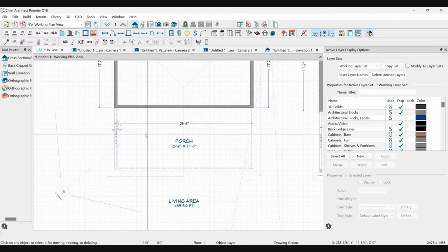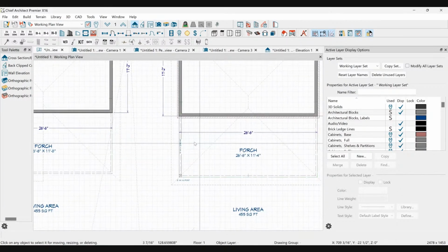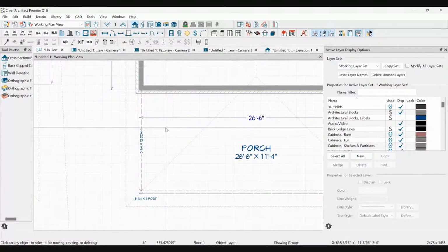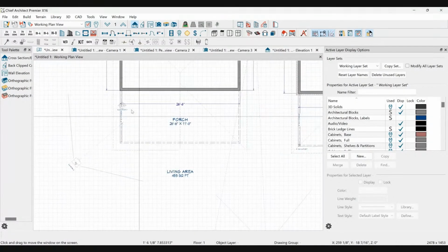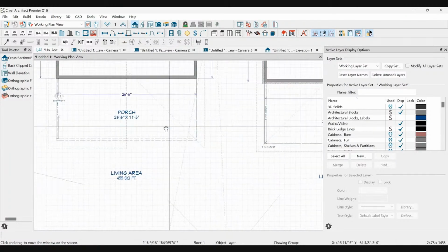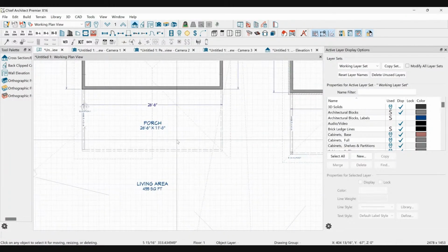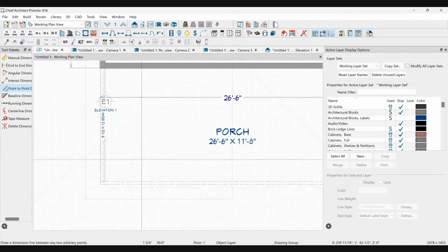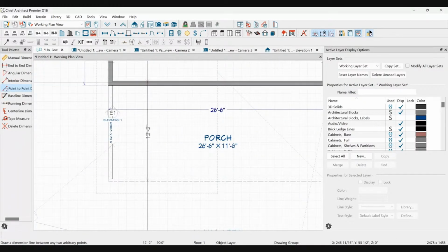So, slight deviation: what happens over here on this house? Because people, when they're drawing these, typically draw lines that represent the beams for the roof, or at least the edge of where the roof geometry happens, which is what the framers need to know. But the foundation guy might need to know something else. Now, in this case, it's the same. The edge of the porch to the edge of the outside of framing is 11 foot 8.5, the framers are going to frame to that number, and the slab guy is going to put the slab to that number because there's no brick going on here.